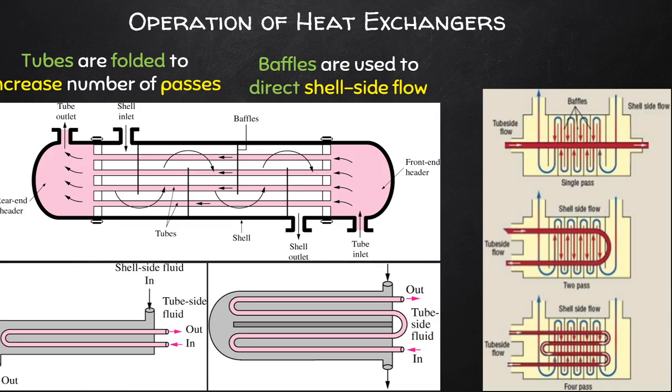It is also important to determine which flow goes on the shell side and which one goes on the tube side. So the criteria to consider are the flow temperatures, the operating pressures, viscosities, as well as flow rates, and what are you doing with the heat exchange in the first place? What are you trying to achieve?